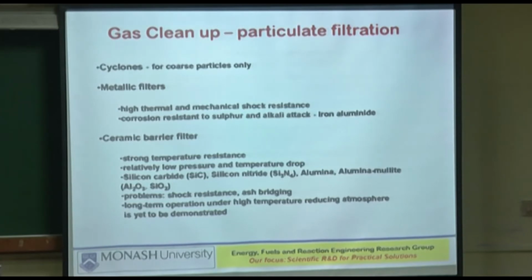The other one is the most important one. In fluid mechanics, you have learned about flow-induced vibration, right? Flow-induced vibration and associated shock is something that the candle filters absolutely detest. They crack like anything, just like toys. And remember that these are very tall items, supported from the top, hanging downwards.